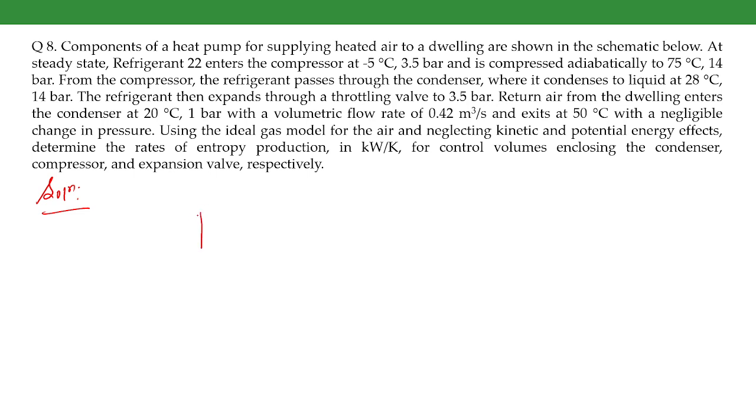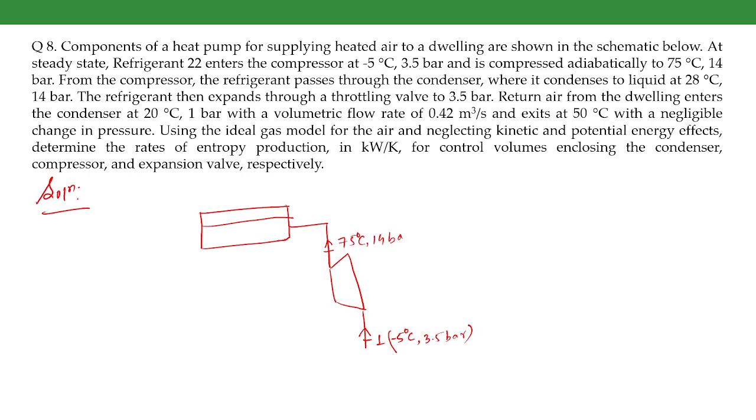This is basically a, let me start with the compressor. Okay, it enters the compressor at -5 degrees Celsius, 3.5 bar. Okay, and it exits the compressor at 75 degrees Celsius and 14 bar in the state point P.